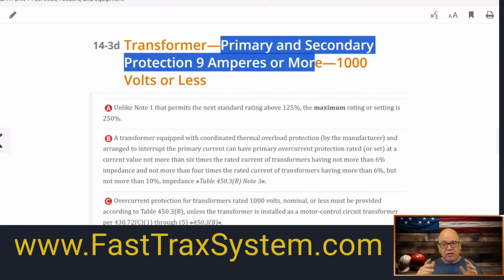Your mindset is, yes, it's possible, but I have to have a unique type of transformer. Again, single phase, one voltage output, or three-phase delta-delta, one voltage, three-wire output. It can't be a 120/240. There is no neutral involved in those. If that's the case, you follow all the rules. Okay, 240.21(C)(1), you're good to go.